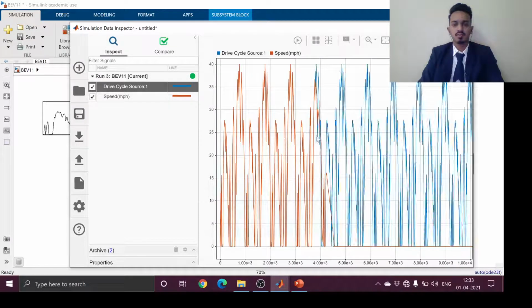it is seen like this. So what our project exactly is: range estimation of an electrical vehicle. As you know, the WLTP class 1 cycle is 64 kilometers per cycle. Therefore, running it 10 times means we have a scope of 640 kilometers, but our vehicle is able to complete only 3.5 cycles. Therefore, considering the first three cycles, it gives around 180 to 200 kilometers